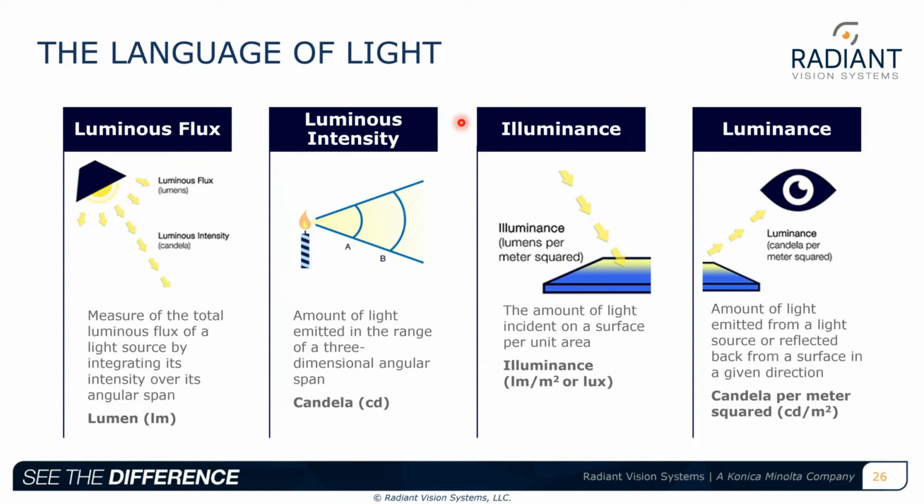And next we might care about the illuminance. So this is the lumens per meter squared, where the meter squared is basically a surface. So if we were designing that light for a hospital, one thing we might care about is if we put these lights on the ceiling, how much illuminance will there be on the table, and how much illuminance will there be on the floor? So both of those, especially in something like the medical field, are going to be highly regulated, because in order for surgeons to do their work, they need to have enough light. And then additionally, it would be considered by anyone designing, let's say, a museum or something. You need to make sure that you're illuminating all of your surfaces.